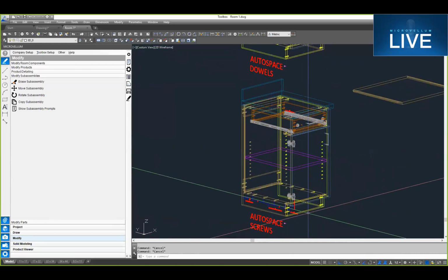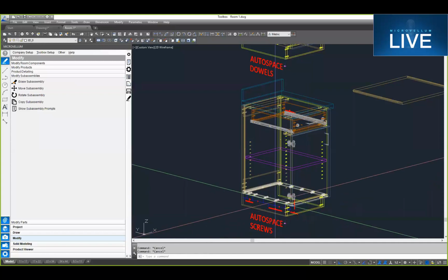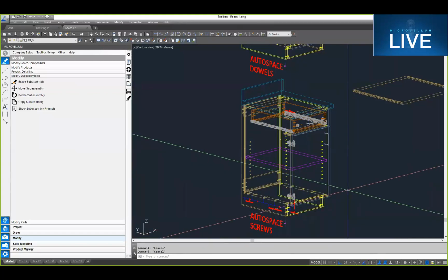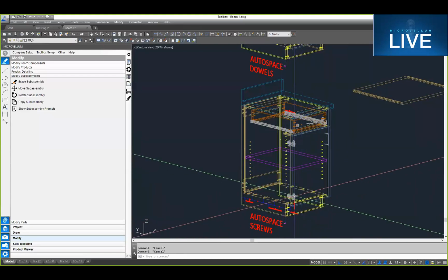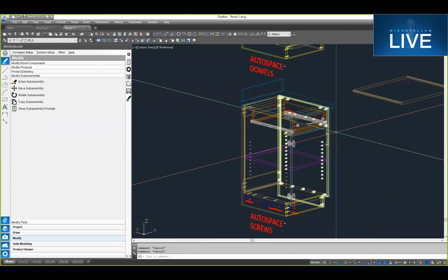But for your tops and bottoms, maybe you're taking those to a saw and cutting those parts out just square, and then taking them over to a second machine, a dedicated horizontal boring machine. That frees up time on the CNC. So if you're looking at ways to improve your throughput on a nest-based CNC, you might consider dowel construction and adding a less expensive horizontal boring machine, as opposed to adding a second flat table CNC machine. Just some considerations when you're looking at what type of construction method.